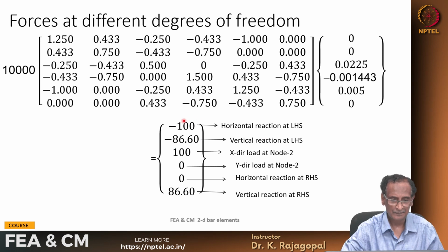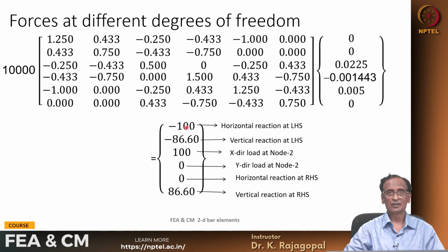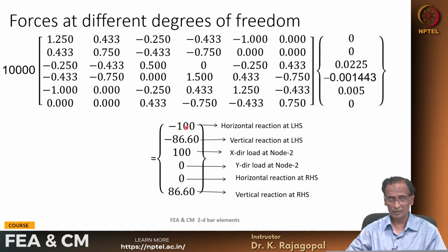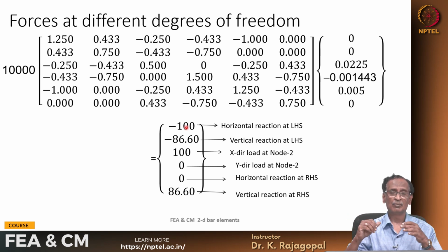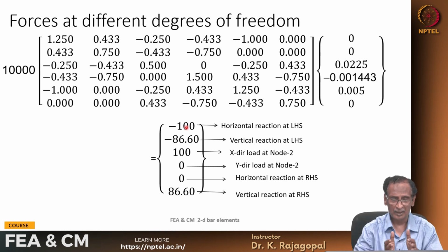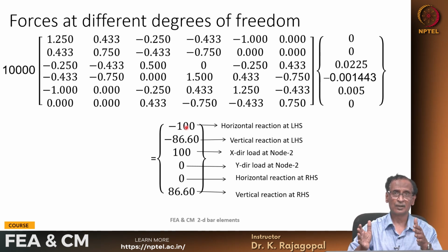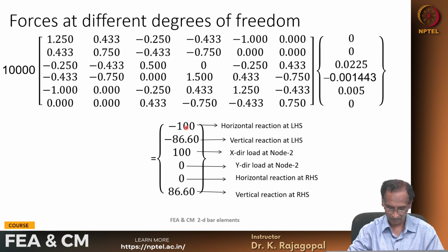We need to design our supports for these reaction forces, and we should make sure that our elements are able to resist these forces without undergoing any tensile yielding or buckling, okay. Because whatever element is in compression, we should check for buckling, and if it is in tension, we need to check for tensile yield stress, okay.